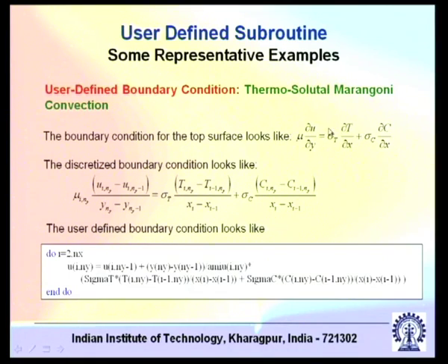This is again a stress tangential to the interface, and these two tangential stresses are balancing each other, but this tangential stress is a function of the normal gradient of velocity, that is what Newton's law of viscosity tells you. This is true only if you have V equal to 0, otherwise you have mu (del u del y plus del v del x). But if you have an interface oriented along x, you have a no penetration boundary condition across the interface, so V equal to 0.